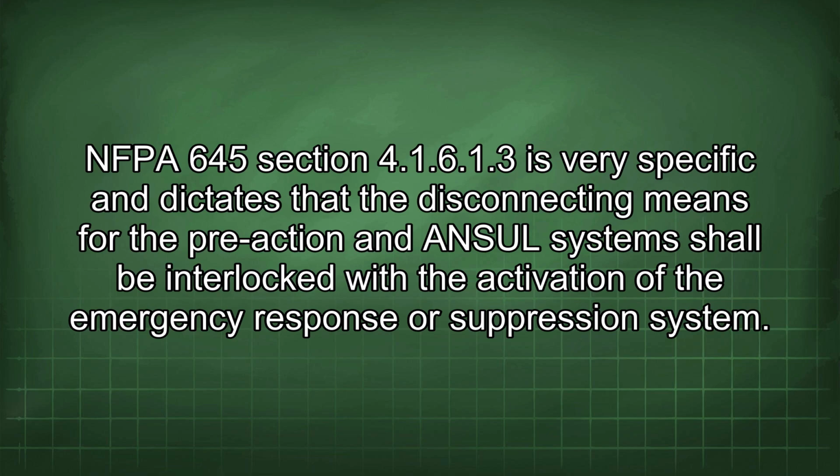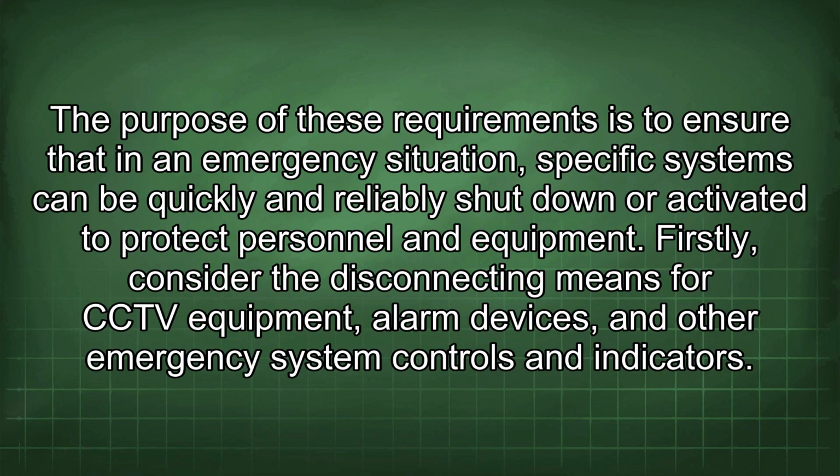NFPA 645 Section 4.16.13 is very specific and dictates that the disconnecting means for the pre-action and ANSUL system shall be interlocked with the activation of the emergency response or suppression system. The purpose of these requirements is to ensure that in an emergency situation, specific systems can be quickly and reliably shut down or activated to protect personnel and equipment.